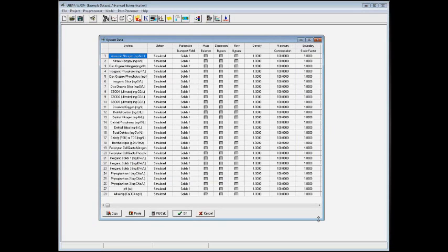And the way we shut them off is, in our case here, we're not going to be doing benthic algae. So I'm going to come down to line 18. I'm going to say, let's bypass it. So we're going to bypass everything that has anything to do with periphyton. And basically, that shuts off the periphyton equations in the model, so the model doesn't even make the calls to those routines. So it saves runtime for you.